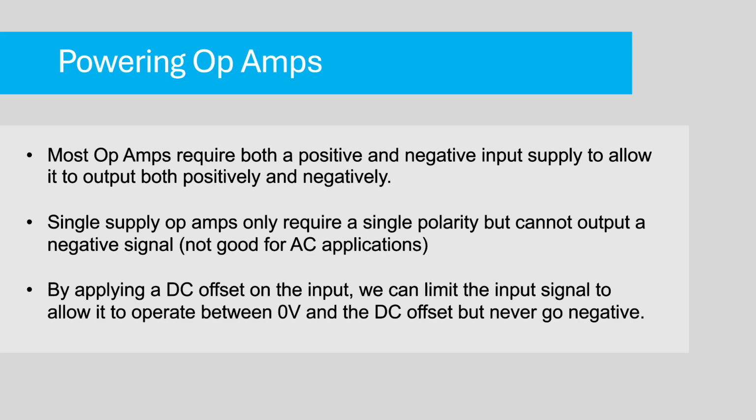When I was talking about clipping before, this is where we would see that clipping occur: it's only going to go up to that DC offset, and then there's nothing above it. So it's just maxed out, fully saturated. Another feature of this is that when we apply it to one of the terminals, that offset brings it up so that it will never go below 0, because it's always offset to 0 or greater.